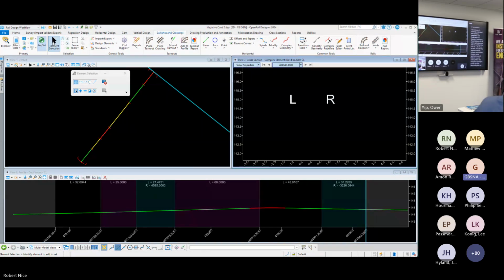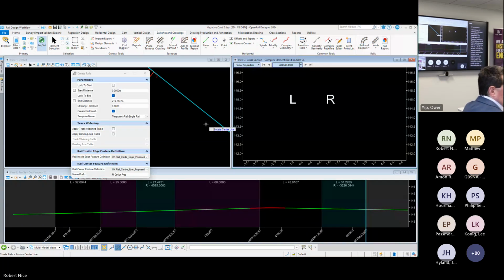So in the S&C kind of workflow, at the right-hand side is sleepers. We want to get the rails, basically the centerline strings. We can do running edge or center, and we want centerline in this case. We want the centerline strings because then we can project those into our profile. But again, just another sanity check before we start exporting this stuff, let's make sure we're doing what we think it's doing.